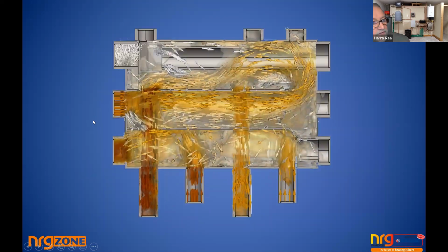So here's what's going on. This is not showing temperature. This is showing flow rate. So the darker the color, the more the volume of water passing. When the flow comes in here from the heat pump, it can't go anywhere else because there are no other connections. This is just a round pipe becoming a square pipe. It comes over to here. There's a suction force here because these zones are calling. It's pulled up here, it comes across down through the zones, the return water comes into the bottom chamber, and the heat pump draws it back. So even though you've taken the flow in the middle chamber, it will work absolutely perfectly to deliver heat out of the top chamber.